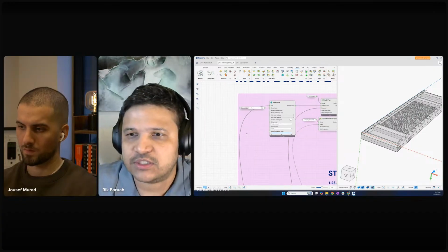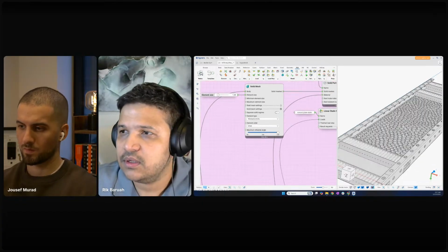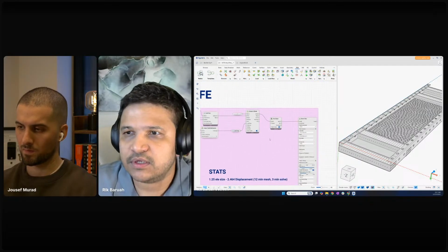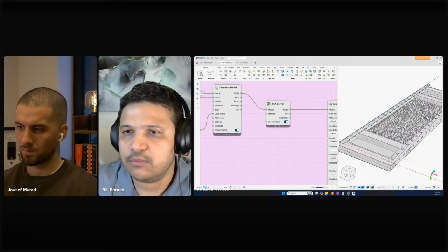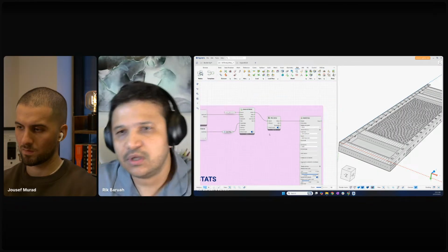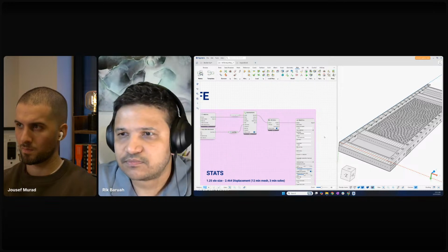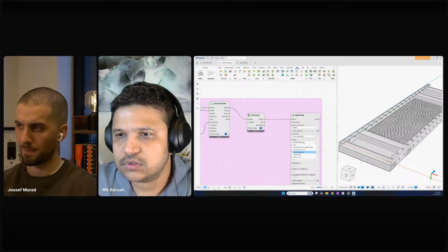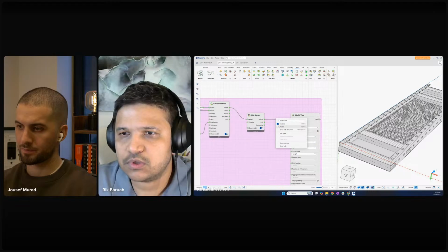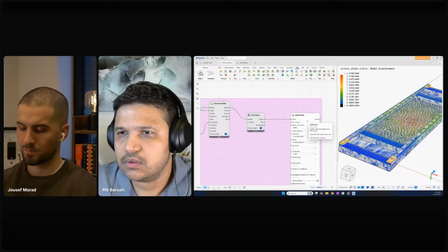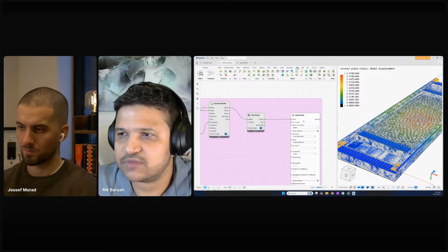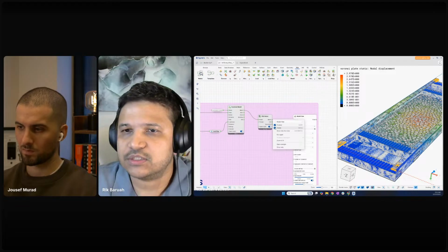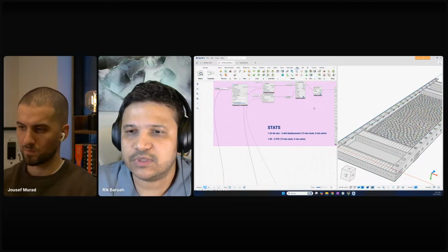So again, for meshing, this one took about 15.5 minutes to mesh. Then you set up the problem. Then you run the FEA solver. Took about 4 minutes to do that. So, all in all, about 20 minutes or so, right? And let me visualize this one. Let's see. Oh, okay, that visualization works fine. Okay, so I'm going to hide that visualization again. On this one with one element size, the nodal displacement was 2.978.